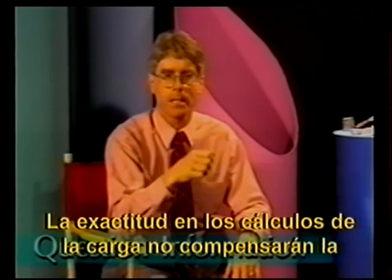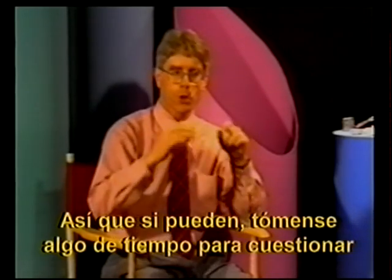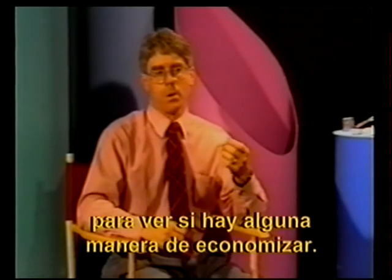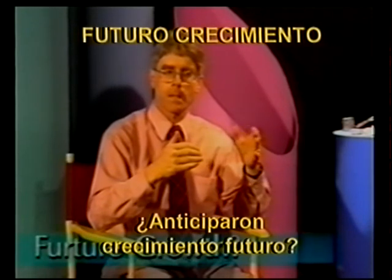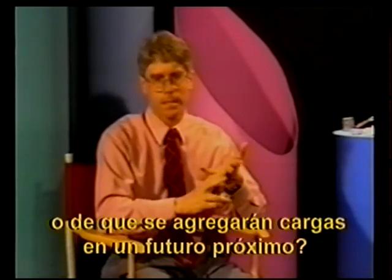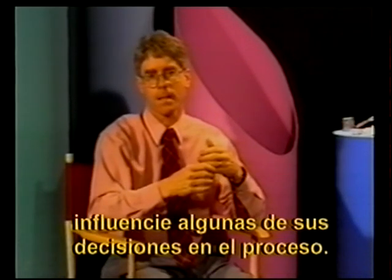Your accuracy in your load calculations won't make up for incorrect information that you started with in the first place. So take some time, if you can, to question both your calculations and the information that you got in the first place to see if maybe there's some way to economize. Some of the things you should take into account: have you anticipated future growth? Is there an indication that perhaps the loads that you're sizing today are going to be used for more hours, or more loads are going to be added in the near future? If so, that should be in the back of your mind and perhaps influence some of your rounding or some of your further decisions down the line.